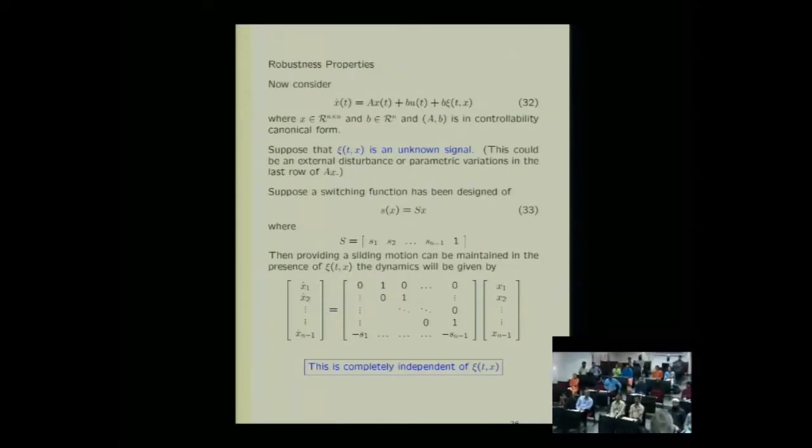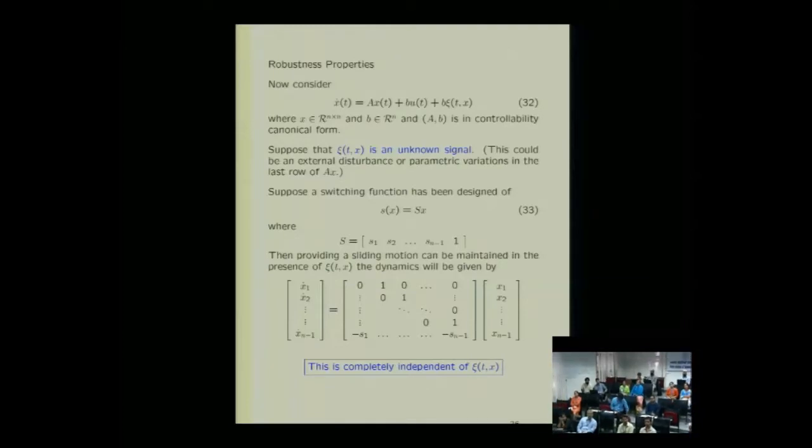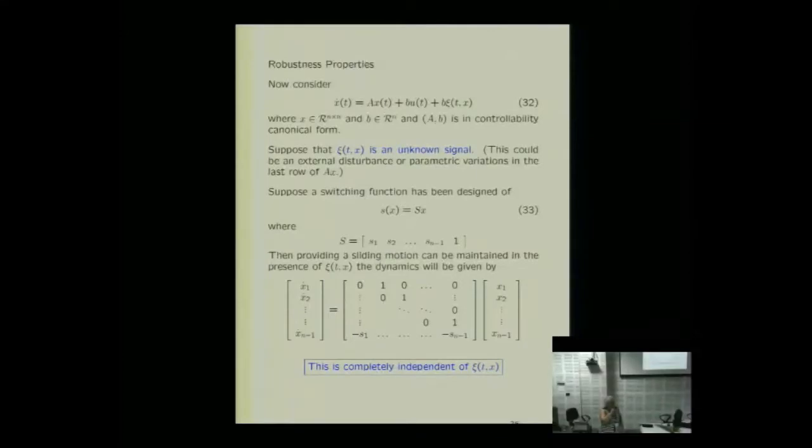I fully get your question. And this is because, in reality, S dot isn't 0. In fact, by switching, it's instantaneously changing with that sign, just as you've said, okay? So it is switching. In fact, it's got infinite rate of change. This is why I urge all my students and collaborators and people I work with to separate those two things, because that equivalent control signal, that notion of S being 0, is rather like an average argument. So it's arguing that on average, if I'm switching backwards and forwards within some band here, on average S equals 0. So the equivalent control signal is a theoretical argument. It isn't the real control signal. There is not a 1-1 mapping.